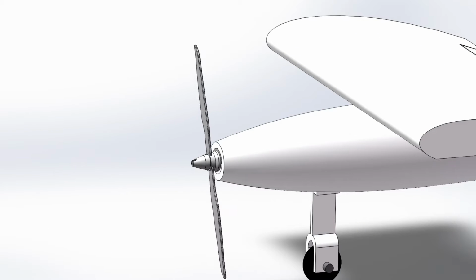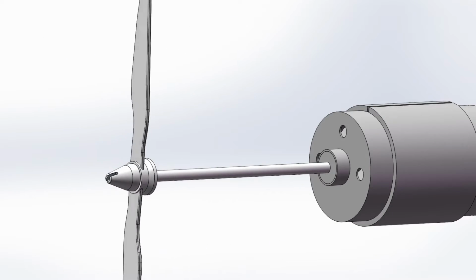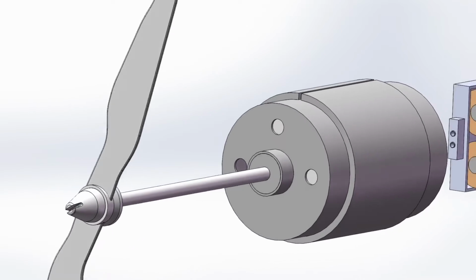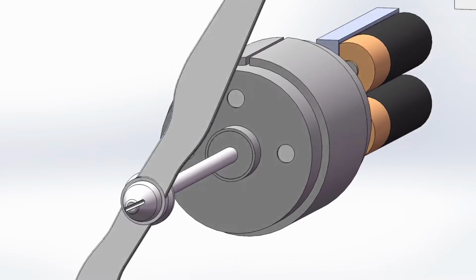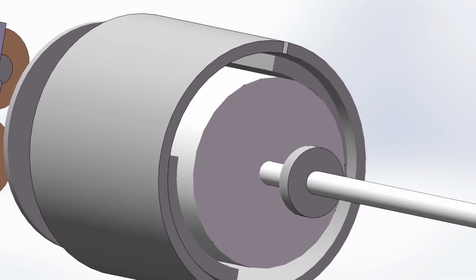The RC plane generates propulsion to move forward using a propeller system at the nose of the body. This system consists of a propeller cap, 2 propeller blades, and a DC motor connected to the propellers with a rotor rod. For the motor to function, 2 magnets are found along its walls surrounding a central rotor containing coils of wires. As electricity from the batteries flows into the motor, it flows through the coils to generate magnetic fields.